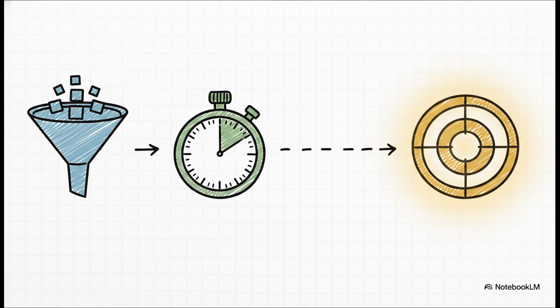And finally, critical WIP, or W0. You get this by multiplying the bottleneck rate by the raw process time. Critical WIP is a magic number. It's the exact WIP level a perfectly balanced line with zero variability needs to hit maximum throughput with minimum cycle time. It's the ultimate ideal state.